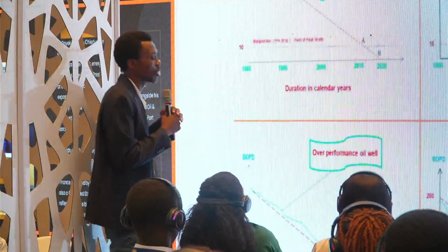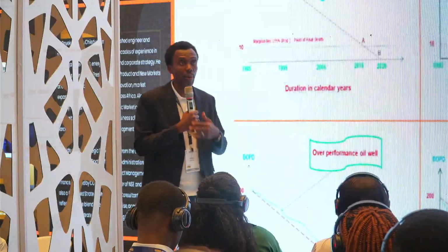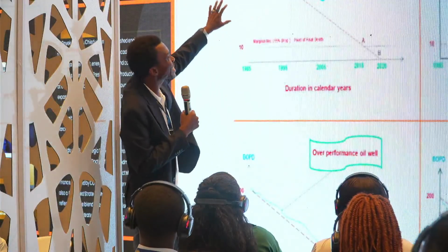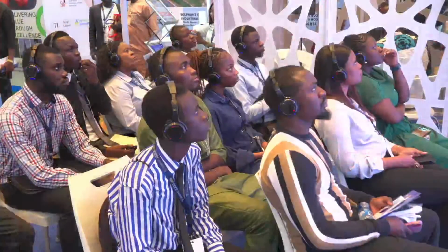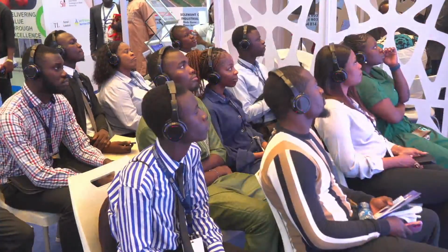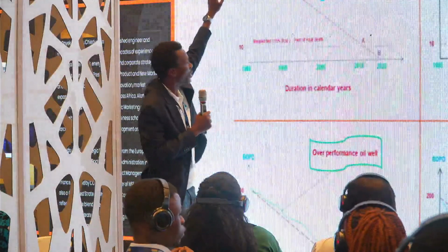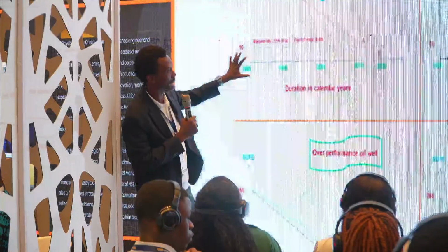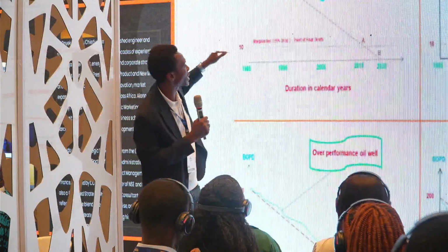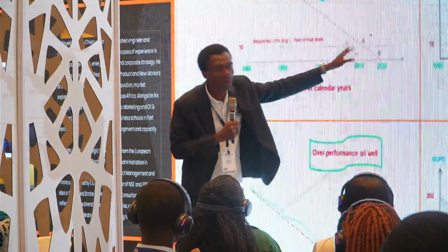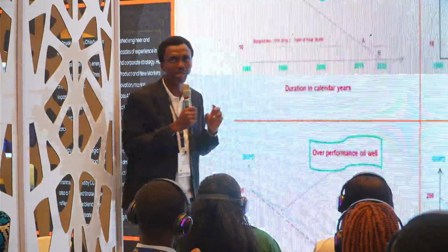Okay, so this is what I was trying to say when I was saying I was going to show you a chart of the life of different kinds of wells that we have in the industry. So first, should be the ideal well. You understand? The first time we perforate it, we case it, producing it to surface. Oh, it's doing 200 barrels. Then after years, so this is 1995. Then when we get to the marginal line, where A is, around 10 barrels. We're just using hypothetical numbers.